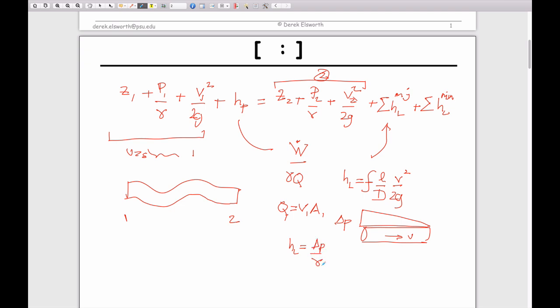Gamma, whatever the fluid is. So you can think of this as being the amount of irreversible loss that you get from driving flow through systems. It's due to the fact that you have shear stresses added along the side of this, which must counteract the flow. In other words, the pressure upstream is larger than the pressure downstream. That potential energy in the system is eaten up by this viscous dissipation, just like me pulling my bag across the table. It uses up energy when it does that through heat, and it has to be resisted against.